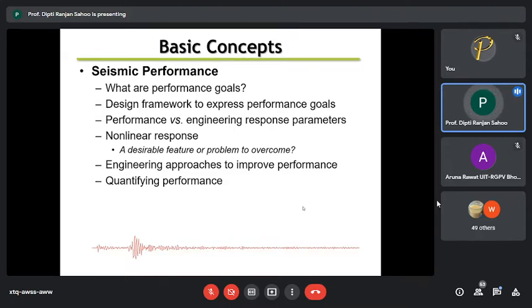So you have 0.87 fy, or your partial safety factors for fck, fy, gamma. That means all your design is linear. What you are expecting during an earthquake is nonlinear behavior. So what is the guarantee that if I follow the current procedure, I will get the expected behavior?